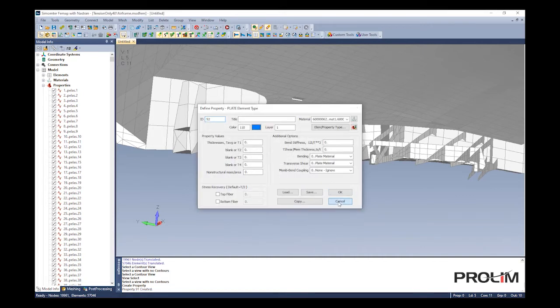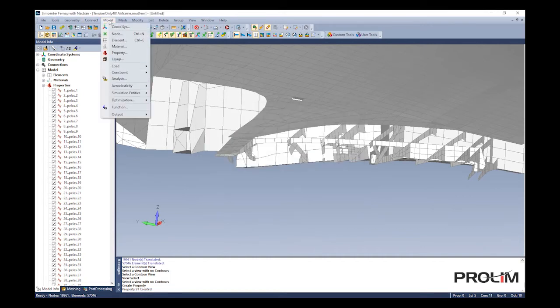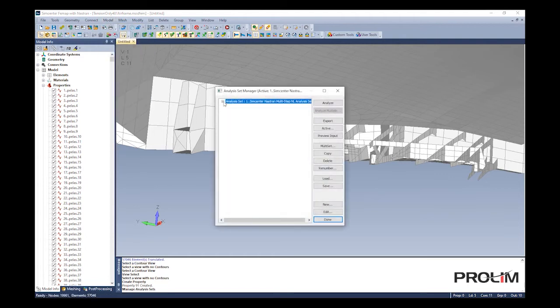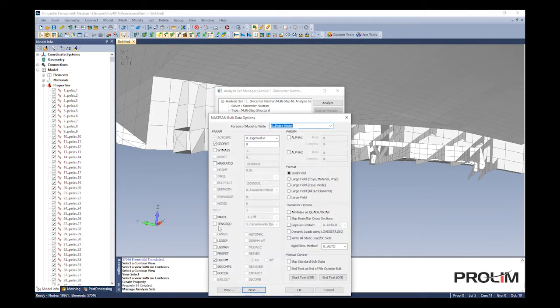Once converted, the element retains shear panel behavior for the remainder of any sequentially independent subcase and any sequentially dependent subcases which follow. After the property extensions have been specified, the TENSQD parameter can be specified in the Analysis Set Manager to control the behavior of tension-only quads.